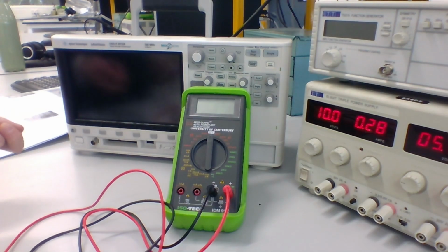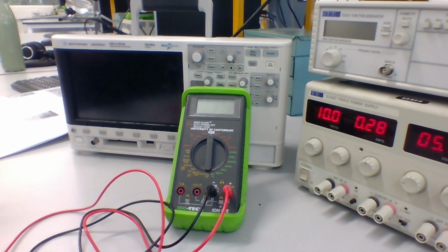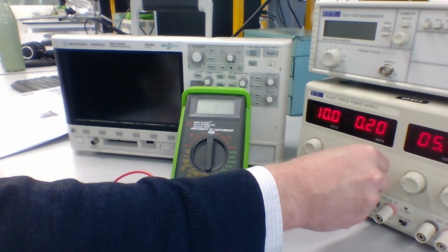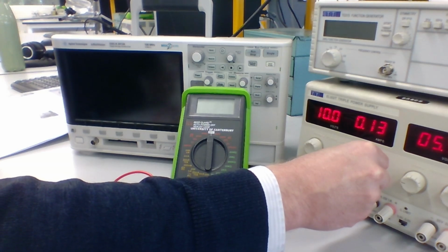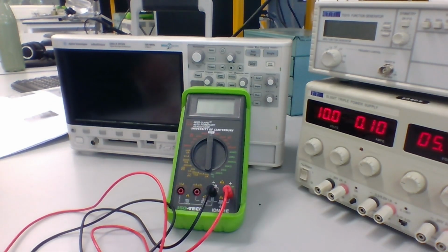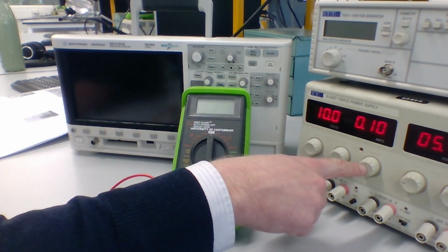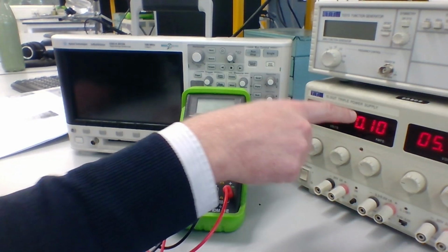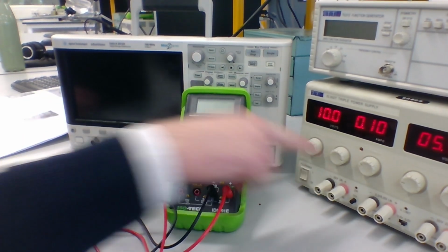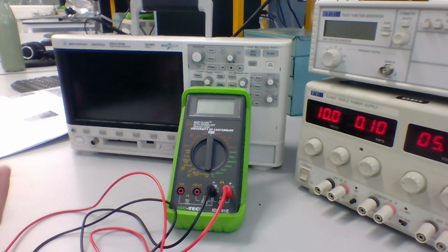What you want to set that to depends upon what you're working with, what you're doing. In these labs we're going to be setting a consistent limit of 100 milliamps or 0.1 amps. And that will be more than sufficient for the labs we do in this course. So I have used the current dial here to turn that current limit down to 0.1 amps. I currently have nothing connected to the outputs of this power supply, so I can turn it on quite happily.